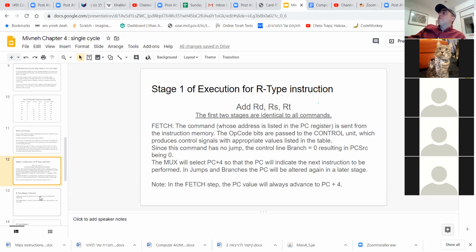Branch is more flexible. It can always go forward and backwards from wherever I'm standing, with 18 bits of movement, because it doesn't copy the first 4 most significant bits of the PC. Whereas the jump, as we saw in the homework, even though it can jump further, is limited by whatever the PC is, and sometimes it will reach a border. It has a hard edge.